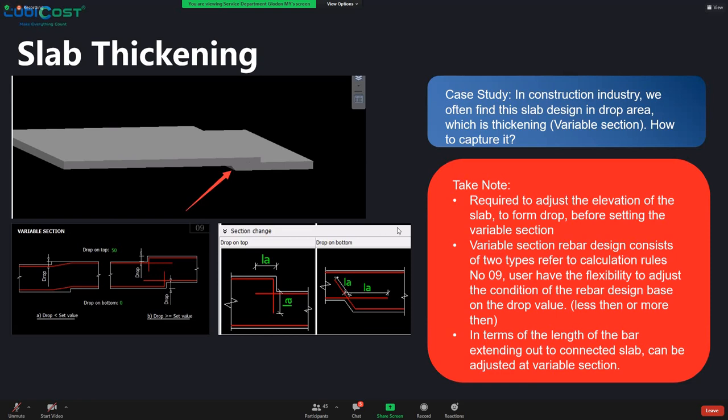Variable section rebar design consists of two types. Refer to calculation rules number 9, which is this one. More than what, less than what, you will follow based on that. If it's more, it will be something like this. If it's less, it will be something like this, in terms of the bar design and how much you will extend. You can actually change it in your section change: drop on top, drop on bottom, how you want your rebar, how much you want your LA to be, and so on. You can adjust these in the particular rules.